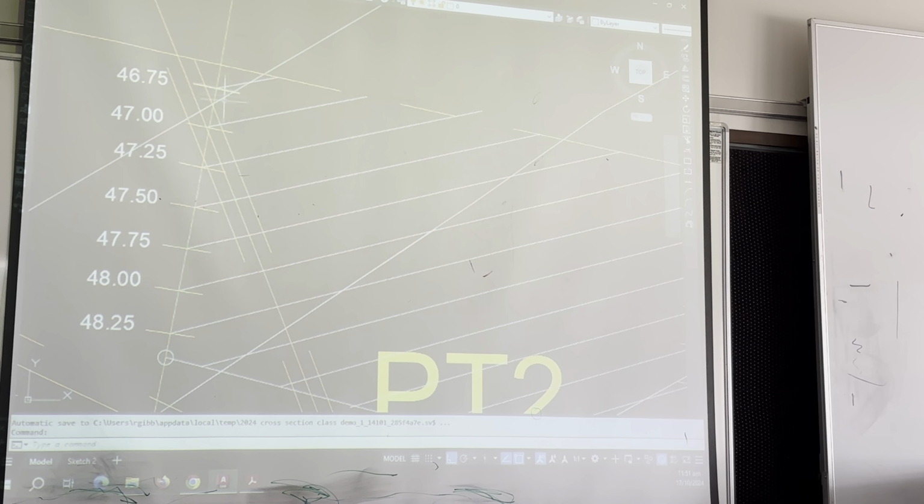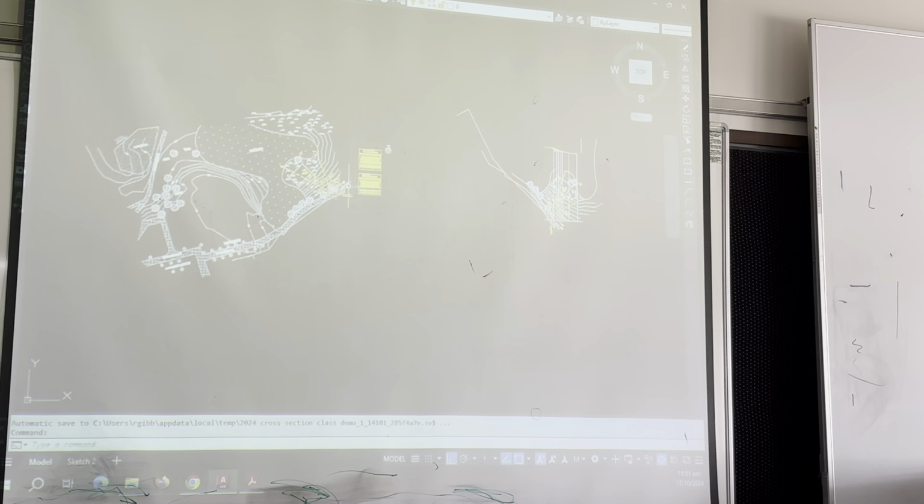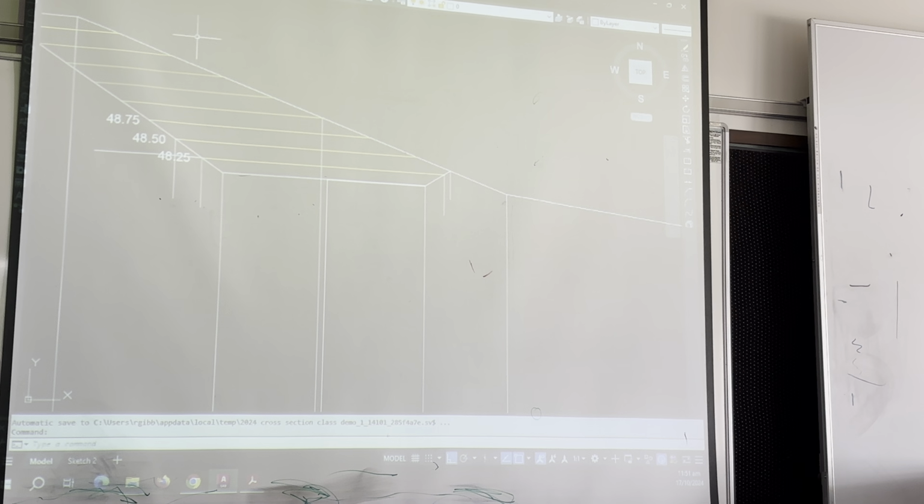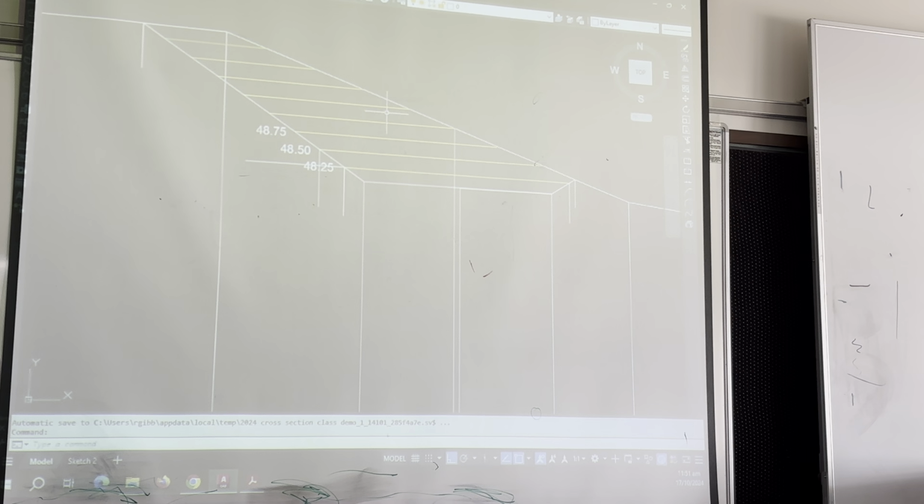And these marks here have been caused by me putting the design contours onto the cross sections. By the way, you don't have to draw these contours on. These are for working out where they go on the road. So what you need on the cross sections is hatching and dimensions, and remember everything comes off the centre line of the road, left and right.